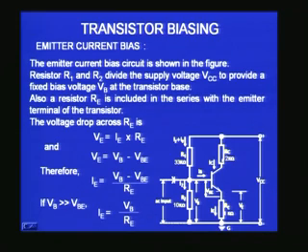So now let us find out what is the voltage VE at the emitter junction, what is the voltage at the collector point, and what is the voltage VB. If I know all of VE, VB, VC and IB, IC and IE, I have made everything ready for the biasing scheme. Now we know what VE is. Most of the application here is the simple concept of Ohm's law. That is what we are going to apply everywhere here.